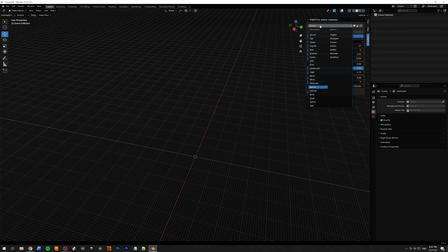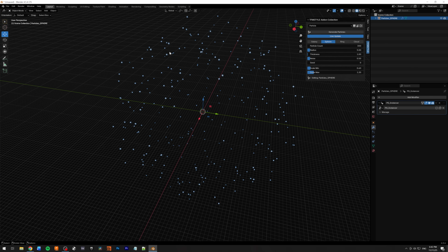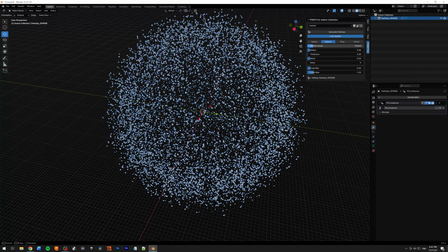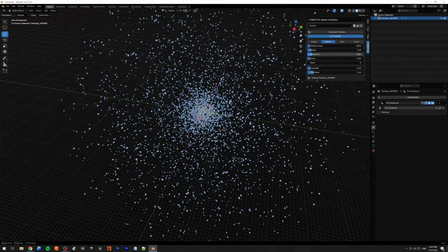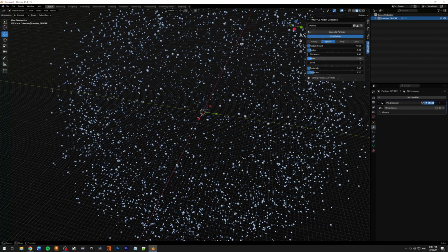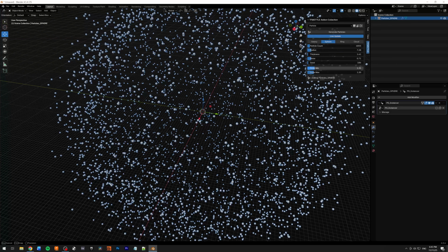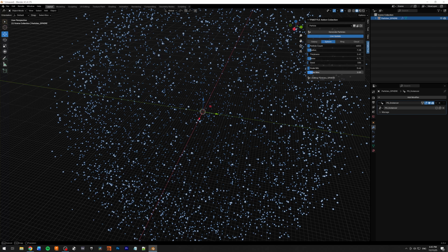The next generator in our list is the particle generator. So again, live update and create particle. This will create just particles in your scene, and you have a couple of options: particle count, radius, thickness, noise scatter, seed, minimum and maximum scale of this particle.